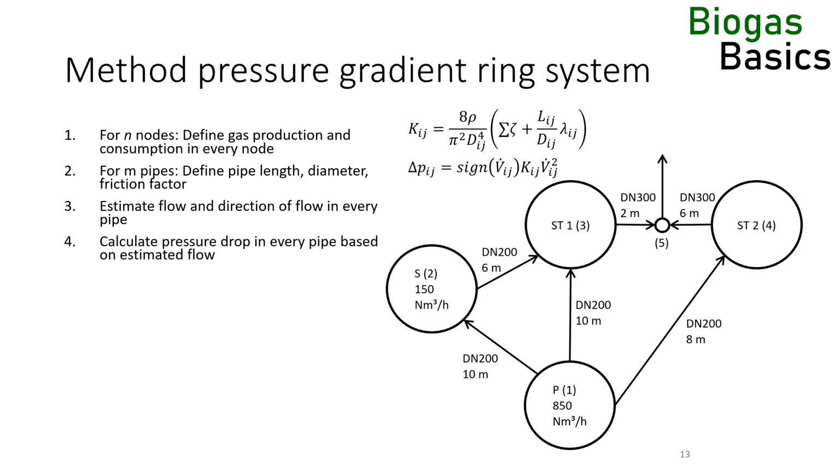The square of the volume flow is always a positive number, even if the flow reverses and becomes negative. The sine function ensures that the pressure drop becomes negative as well in this case. The friction factor of the pipe does change slightly with the flow, but the changes are small and can be ignored for this purpose.